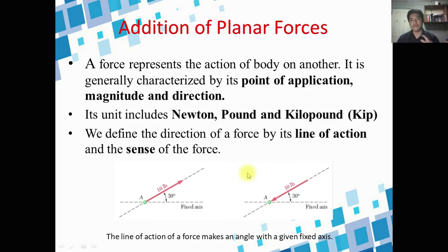What is a force? A force is simply a push or pull, what we have learned in physics. But here in statics we're going to study the deeper meaning of a force. A force represents the action of one body on another. So if you apply a force to a certain particle, you are actually having an action of one particle on another particle. It is generally characterized by its point of application, magnitude, and direction.